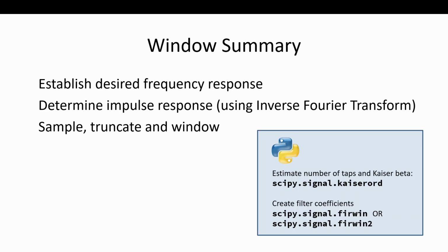This is also a very good go-to filter design approach when you have minimum resources, because it takes minimum resources to compute your coefficients or recompute them. So if you have an application where you want to dynamically change the filter, then this is a great one to do versus some of the other methods I'm going to show you. But the other methods I'm showing you are for when you have a computer there, you're designing your filter, and you just want the coefficients, and you're going to put it into a device. Then we're not worried about that, and you use those other approaches.